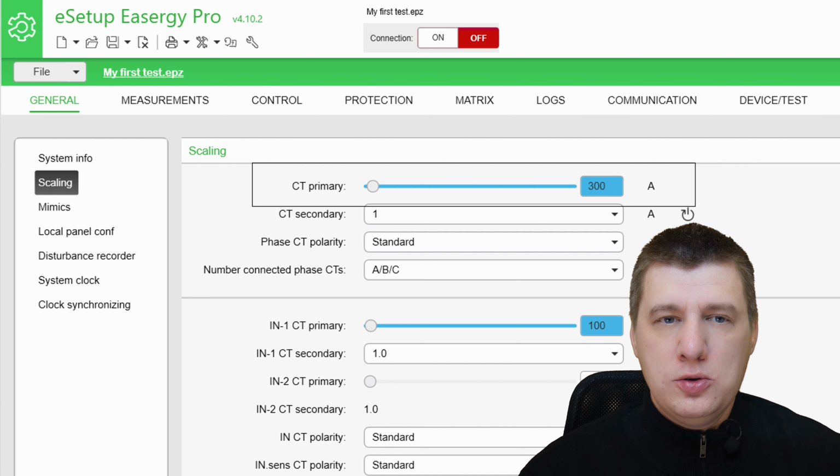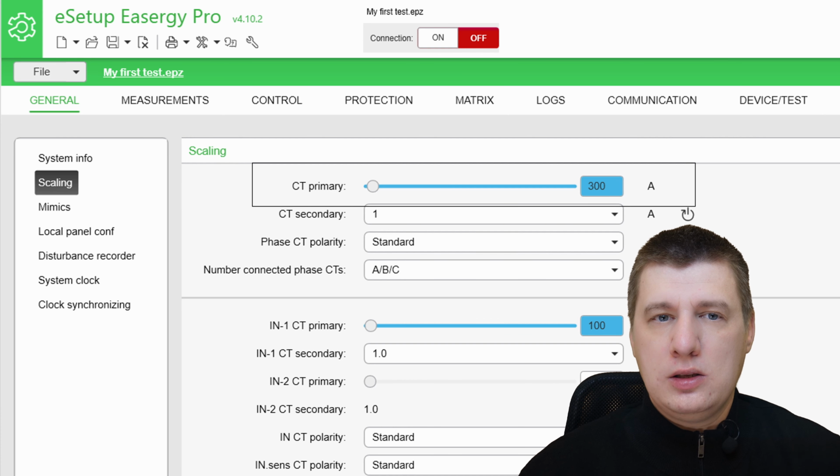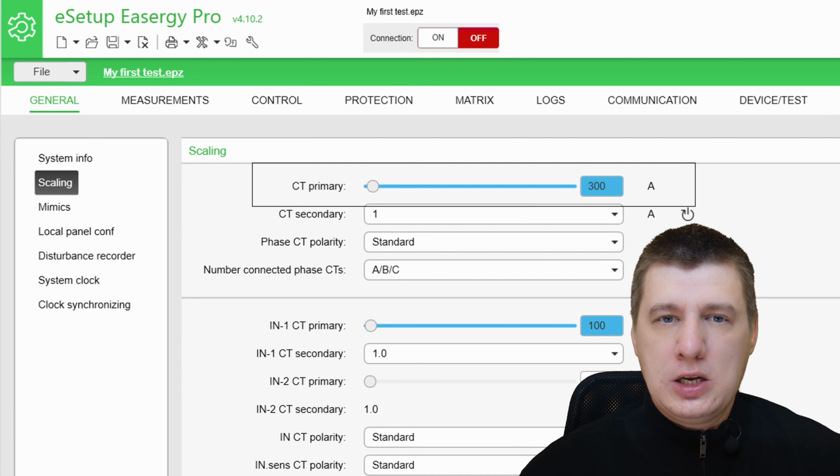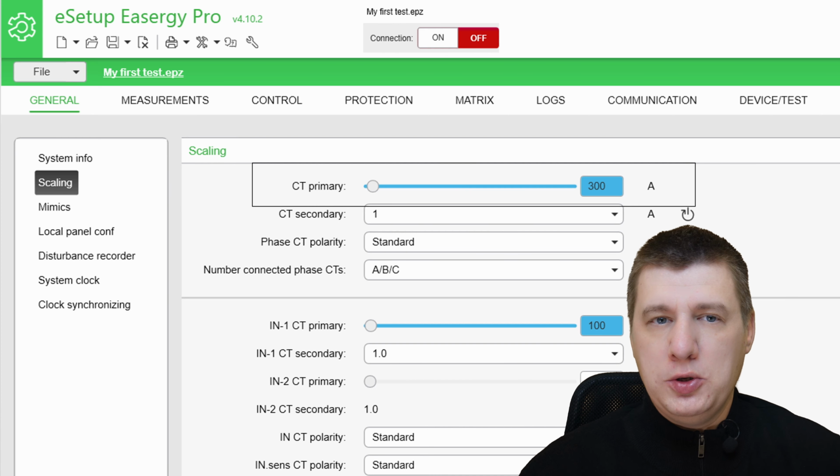You must never energize the primary circuits before the CT primary and other scaling settings are properly configured. Failure to do so can result in death, serious injury and equipment damage. To ensure the scaling remains accurate during the fault, the CT must be sized to avoid saturation. For definite time protection, the current must be greater than 1.5 times the set points.